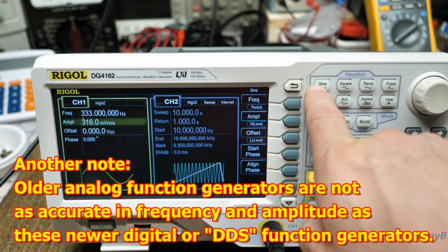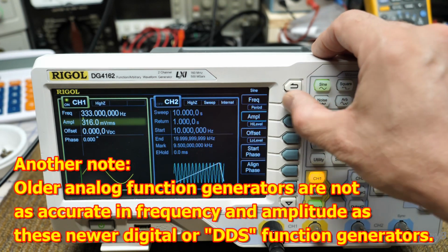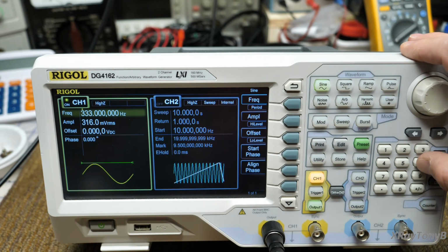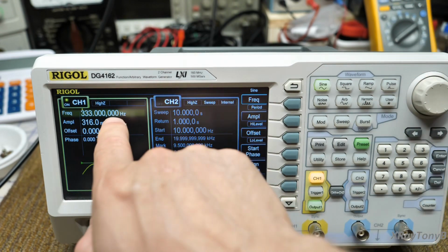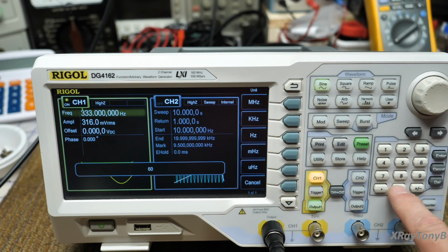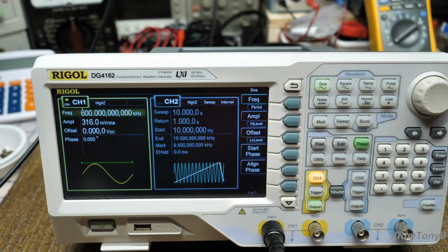So if I turn this sine wave on and I hit output, let's say we want to generate an AM radio signal at, let's say, 600 kilohertz. So I'll go to frequency and I'll type in 600 and see this comes up here, and I'll hit kilohertz.